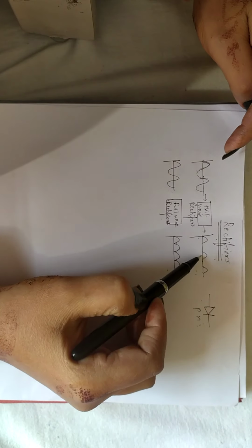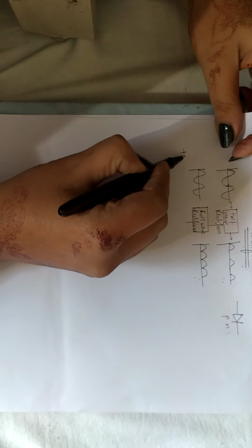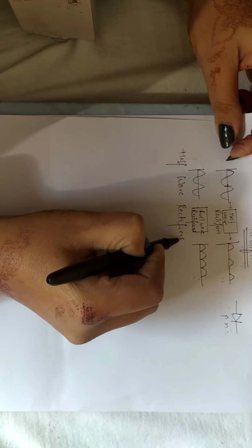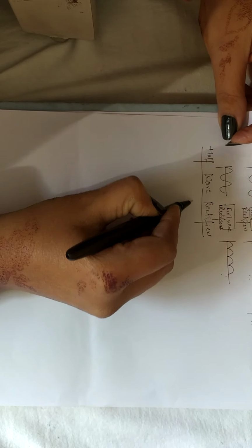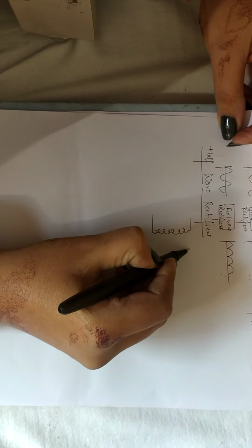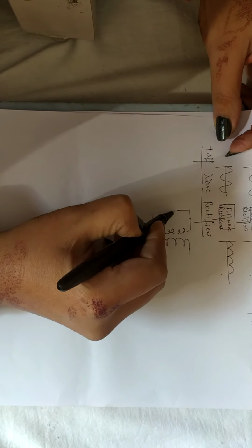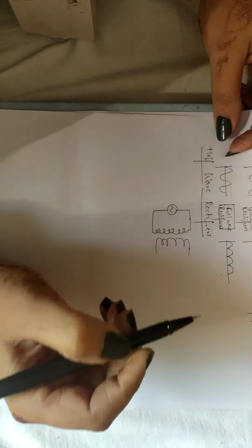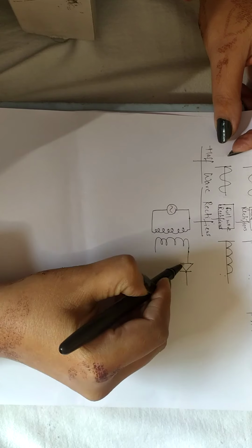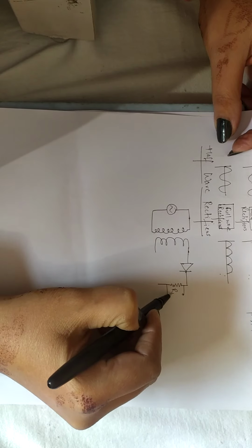Now let us see how this waveform is obtained from a half wave rectifier. First we will discuss the half wave rectifier. This is the circuit diagram for the half wave rectifier. There is a step down transformer. This is the primary coil with more turns, and this is the secondary coil with fewer turns, to step down the voltage. Here we apply our AC voltage, whatever voltage you want. In the secondary circuit, a single diode is connected, and the output is obtained across the load resistance, say RL.